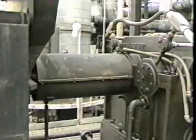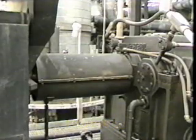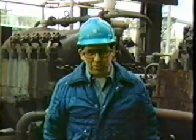The driver is connected to the compressor, or gearbox, through either a flexible diaphragm coupling or a gear coupling. The coupling allows for small misalignments between the two rotating shafts. And that's a typical centrifugal compressor.